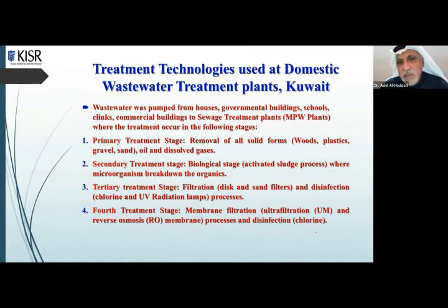In this stage, biological treatment is running. It's divided into 2 parts, the aeration tank and the secondary clarifier. In the aeration tanks, we are trying to activate aerobic bacteria, which in the presence of oxygen eat the organics as food and break them down. So after the water passes the secondary stage, all these things will be removed, and it goes to the tertiary treatment stage.